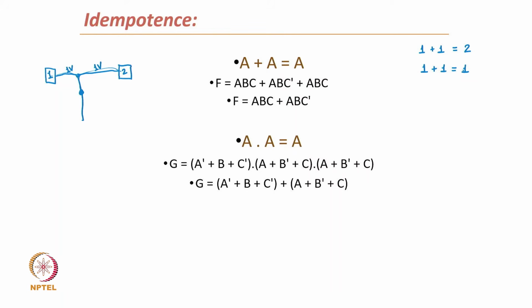So, the resultant voltage is only 1 volt. It is not actually 2 volt, voltage will not add up, this node is just driven by 2 voltage sources of 1 volt. So, if we think about our electrical logic networks, then this Boolean algebra makes sense. We have A plus A is equal to A only, it is not 2A.